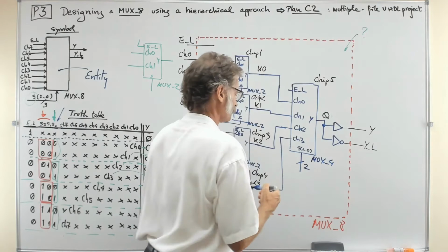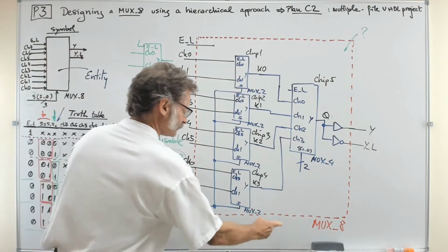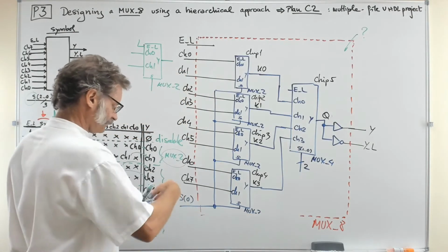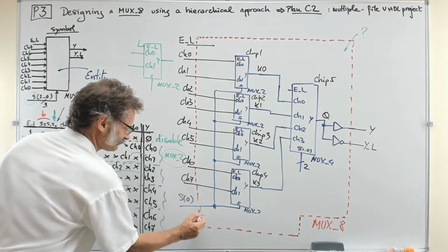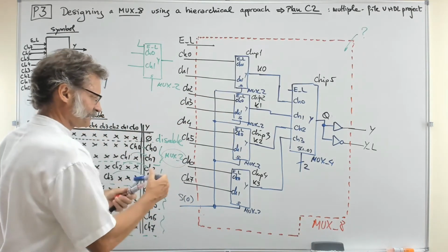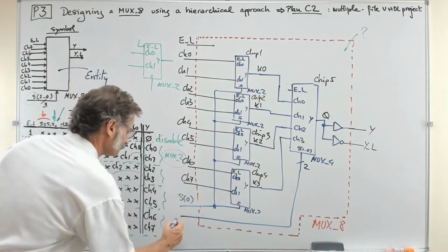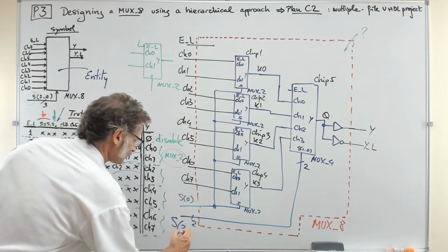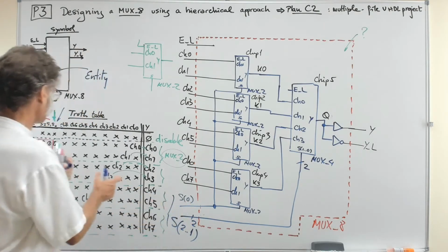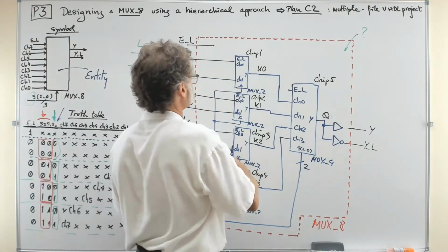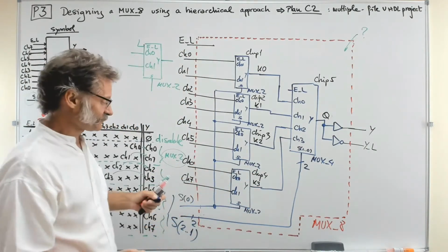This MUX4 naturally has to go to the input, and you can now modify the boundary of this device, make it practical, and now you can do that connection very easily. You see, you have 2 more wires to connect here, so this is 2 wires, so this is S2 down to 1. So you've got it, 3 wires for selecting, because you have 8 channels connected in this specific way, because this is what you want.